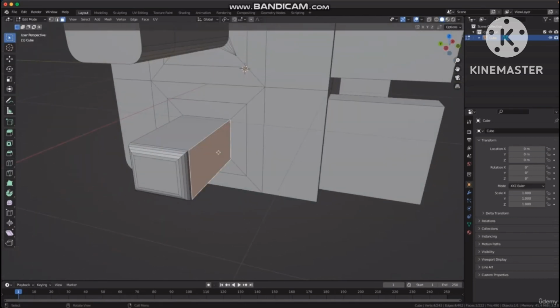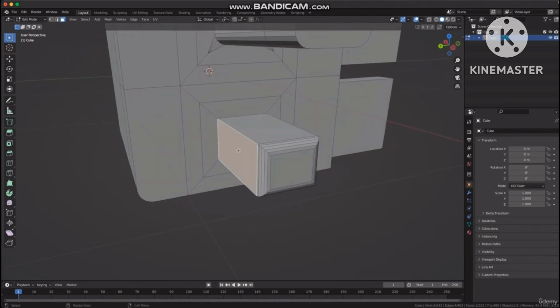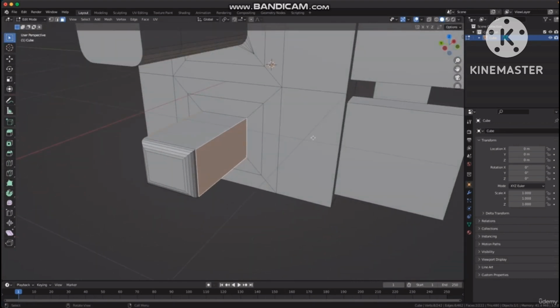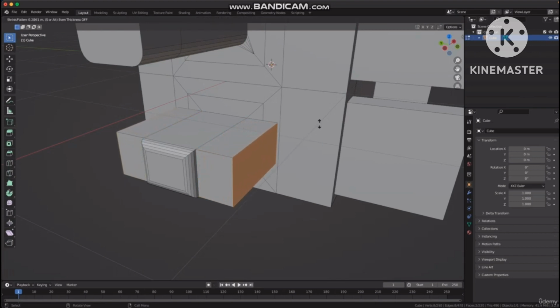So to do that, we have actually different types of extrude that you can use. So this is a little bit more advanced, but it's really nice to know that it's available. So I'm going to select this face again, shift, click this face again. So we got these two faces selected. Now, instead of pressing E to extrude, I'm going to press Alt E. So hold Alt, press E. This is going to bring up the extrude menu. And now you can see we got these different options or different types of extrusions. We're not going to go into all of them. I'm just going to show one of them, and that is extrude individual faces. So if I click this and I move the mouse, you can see we are now extruding both those faces in the correct direction where they are facing towards.